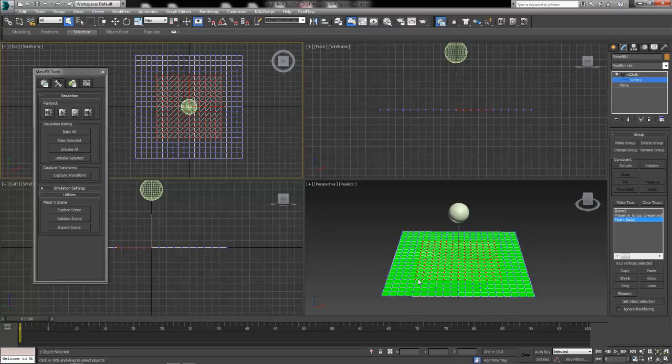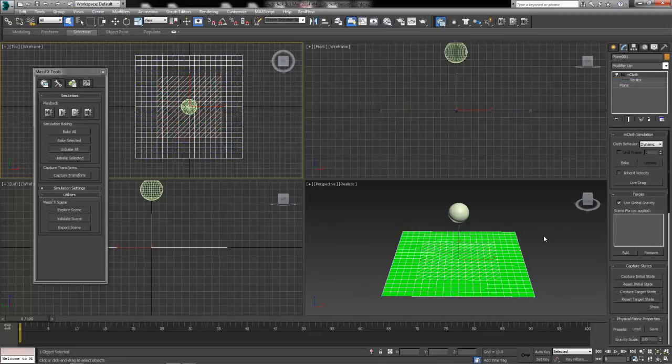It also kind of tessellates your polygons for you. It'll add that diagonal shape throughout all these things as well. And then you'll be able to see, if we turn this off, exactly where your tear group is located, as well as get some more ragged or more correct tearing happening, because we don't want it to tear along just the edges of our boxy shapes. We like to give it the option to tear some triangles and stuff in there as well.